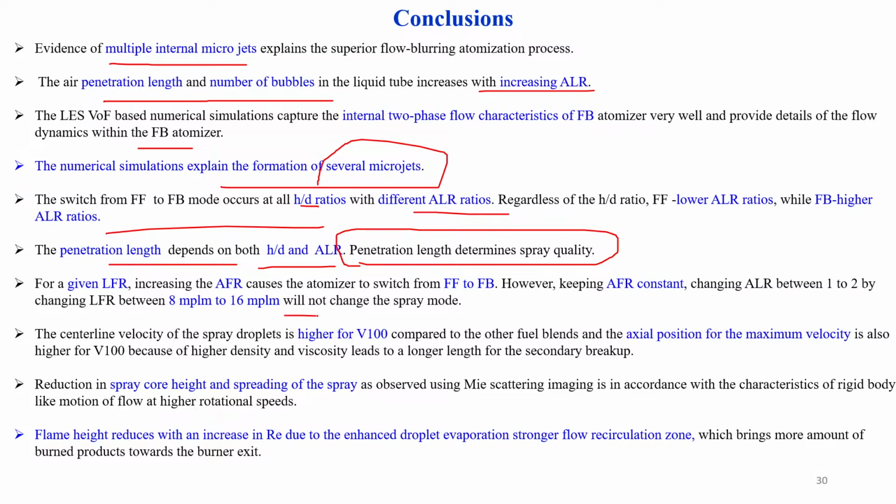Here are the different important parameters. Vegetable oil shows an increase of 100 percent compared to kerosene. We need to do preheating to understand the viscosity and density, and then we can bring the spray quality very high by adding the preheat.